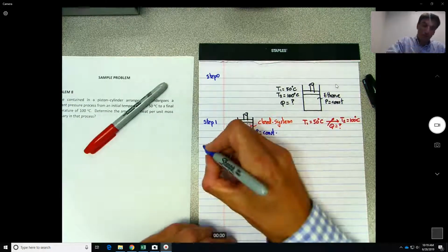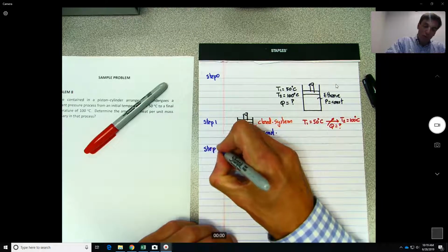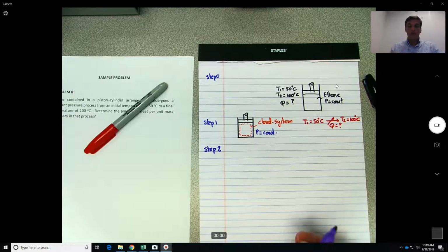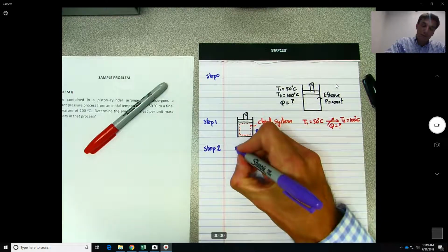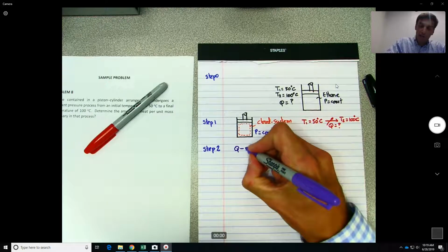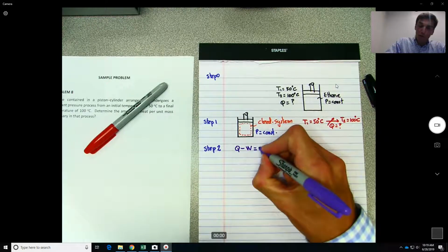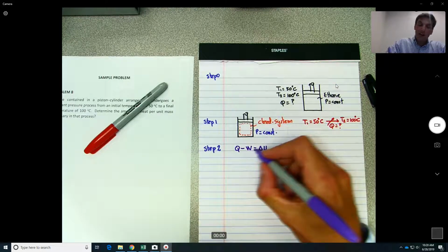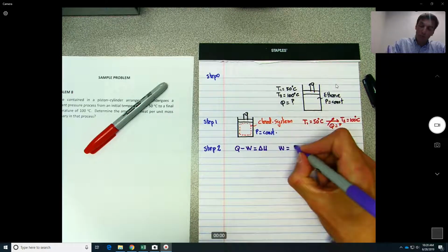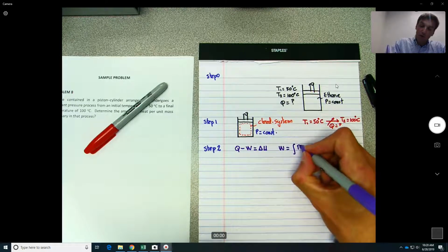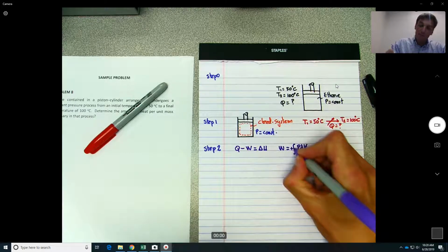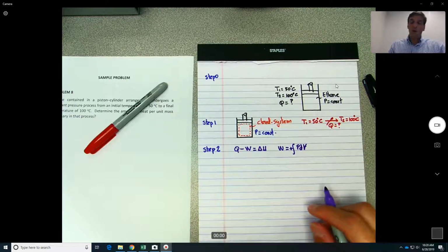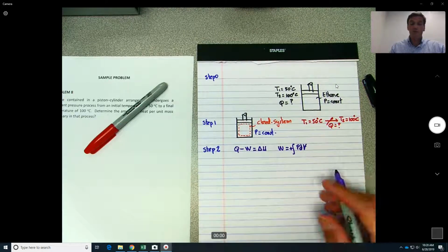Okay. So step 2, applying the first principle of thermodynamics. There are different sign conventions, but in this case we use Q minus W equal to change in internal energy. That's neglecting kinetic and potential energy. And using this definition, we know that the work done by the pressure is equal to positive P dV. Okay? All right, so over here there are 2 ways to solve the problem, and we're going to solve it both ways.